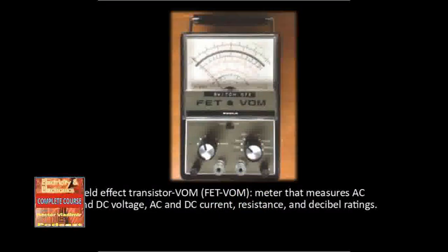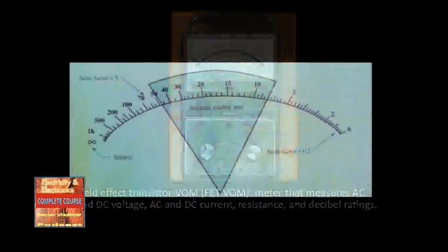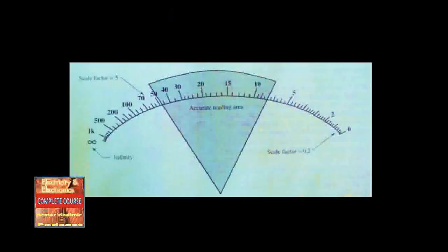Did the needle move too violently? If so, the meter range selector should be changed to a higher range. Remember, you should start on the highest range when you're not positive on the voltage or current values. The flash check will save you many dollars in meter replacement and repairs as well as wasted time. A meter has its greatest accuracy at 2/3 deflection of the meter scale. Use the range that reads as close to this deflection as possible.